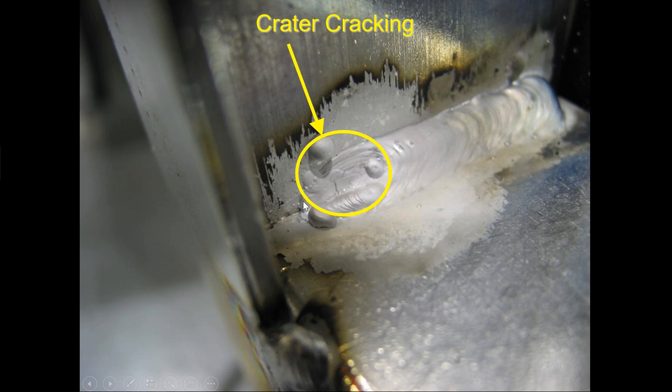The correct answer is to start here. Start closer to your edge, get it hot, and then weld back this direction, because you're welding to sound metal. Your edge where you start off will be nice and clean. It'll look like the beginning. So it'll be like a beginning here and a beginning here. Again, trying to respect that crater condition.